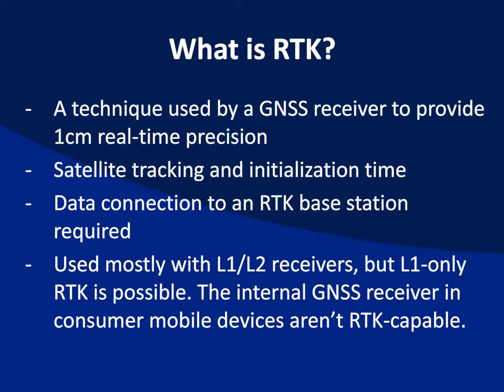And just like 10 or 15 years ago, when people would talk to me about, hey, my RTK is not working, the thing I always point to is the communications, and that's always been the issue that I've seen. That's the first thing I ask folks about. And it's no different today. The difference is, 10 to 15 years ago, we were using either 900 megahertz radios or UHF radios, and some people still do today.